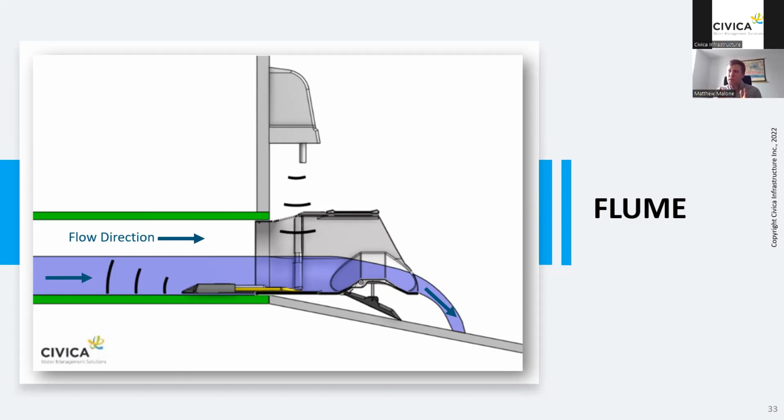We would typically pair this with that area velocity meter, so that it can work in higher flow conditions when the flume's overtopped. And we can also put in a depth sensor to measure the depth. Based on the relationship between the depth at that point behind the flume, we can get a very accurate measurement of flow in these systems.